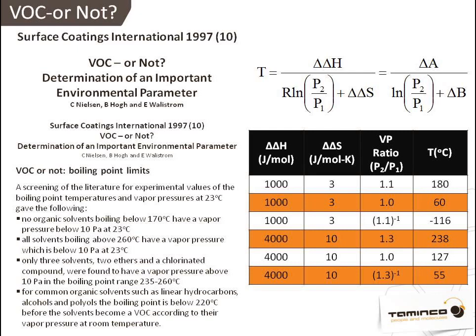And again, you can take this equation for the straight lines and you can calculate this. This would be the volatility divergence. This is a 10% difference in volatility across the range. This is a 30% difference in volatility, meaning one molecule is 30% more volatile at one end of the range and it becomes 30% less volatile at the other end of the range. And the values you see here are for a temperature range of about 300 degrees C and about 180 degrees C. And again, this is only important if this inversion is occurring at a relevant temperature. All these lines are not perfectly parallel, and there'll always be an intersection of these two lines. But if the intersection is at 3,000 degrees centigrade, or if the intersection is at minus 100 degrees C, it's irrelevant. It's only when these volatility inversions occur at around room temperature to maybe 200 degrees C that they have an impact on practical VOC definition.